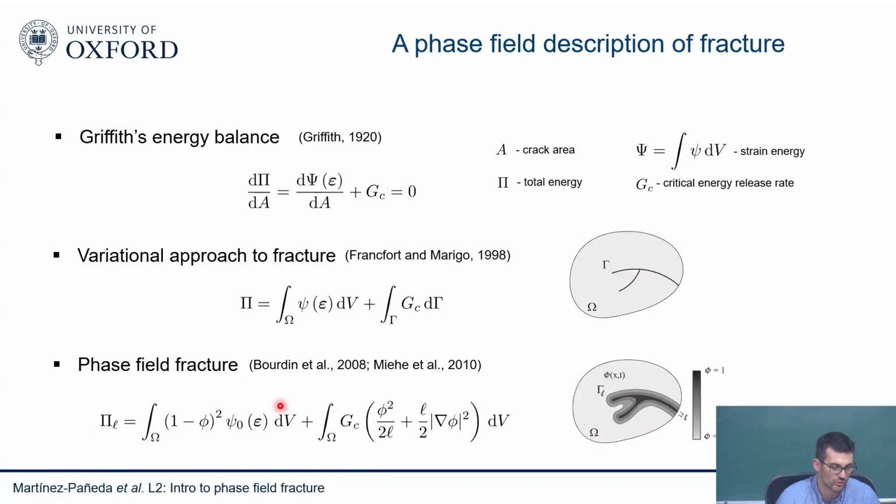One is that, of course, like any sort of continuum damage mechanics model, the phase field is like a damage variable, so 0 for uncracked material points, 1 for fully cracked material points. So you are degrading your stiffness. When you have full damage, there cannot be any stiffness left, right? Remember the Griffith and the bar. The bar loses all load carrying capacity when it's fully cracked. So the same goes here. What form you use to degrade, we normally use this quadratic form, but it's up to you. You can pick a different one.